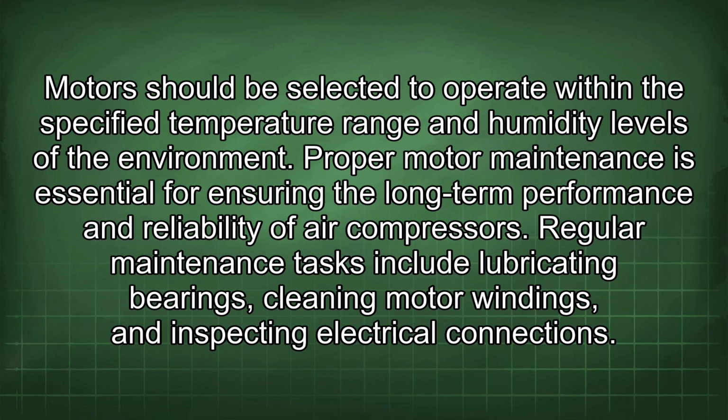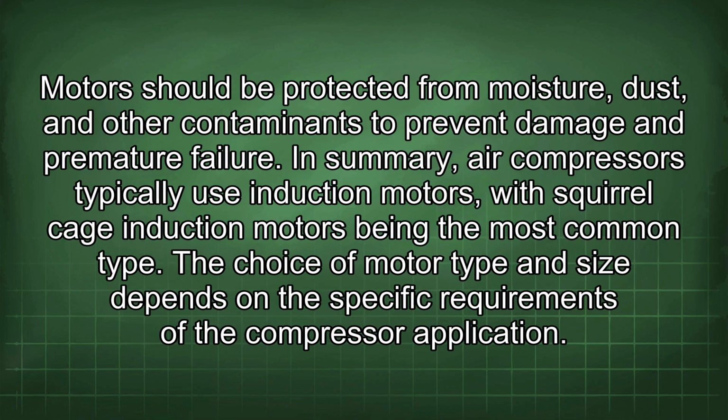Proper motor maintenance is essential for ensuring the long-term performance and reliability of air compressors. Regular maintenance tasks include lubricating bearings, cleaning motor windings, and inspecting electrical connections. Motors should be protected from moisture, dust, and other contaminants to prevent damage and premature failure.